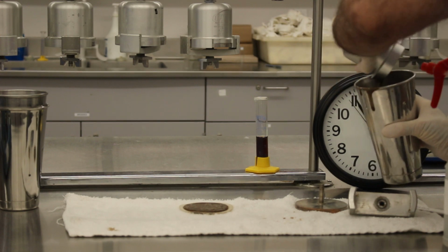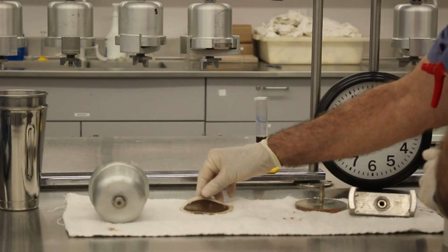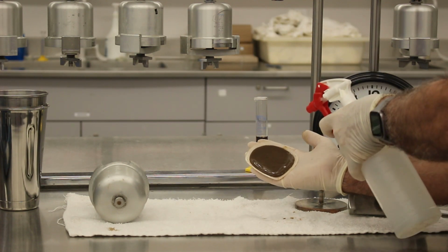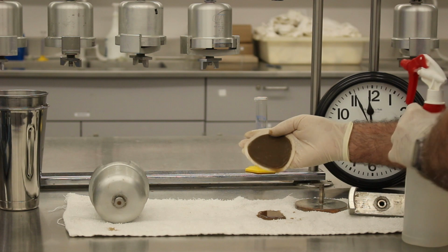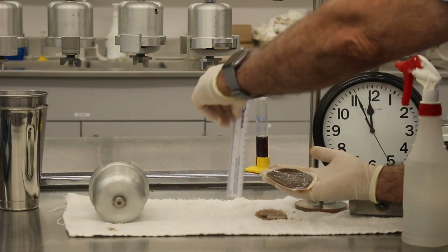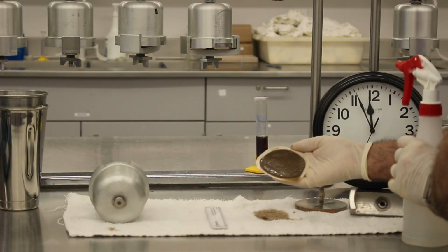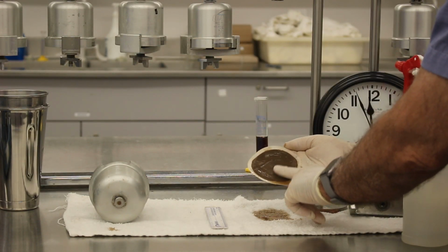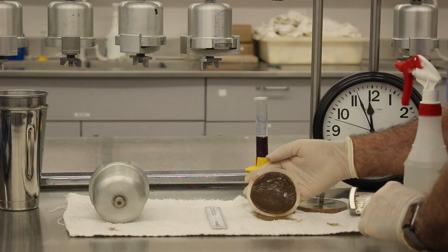Wash the filter cake on the paper with a gentle stream of water and with diesel oil in the case of oil-based muds. Measure the thickness of the filter cake. Report the thickness of the filter cake in 32nds of an inch. Although standard descriptions are virtually impossible, such notations as hard, soft, tough, rubbery, and firm might convey some idea of cake consistency.